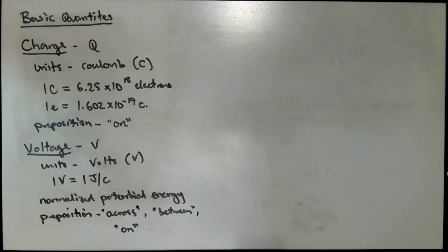So you always have 2 leads that you use to measure voltage, a positive lead and a negative lead. And if the negative lead is always attached to, let's say, some conventional reference point, like ground, that's taken to be the sort of 0 point of potential, then we can talk about the voltage on a node or something like that. But please be aware that saying something like the voltage through a component is just not coherent.